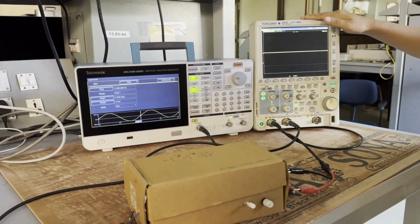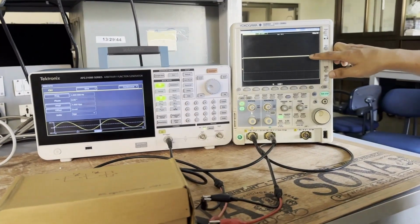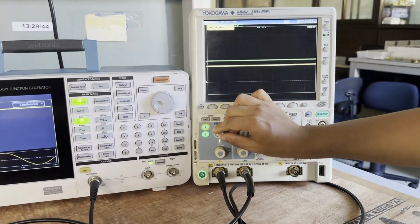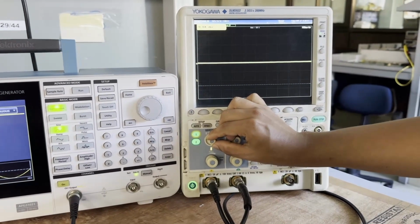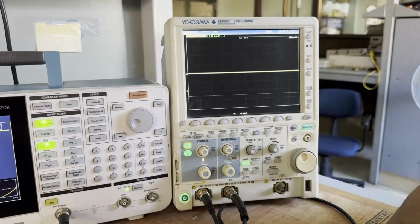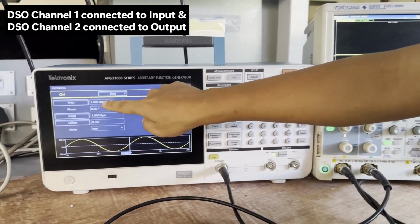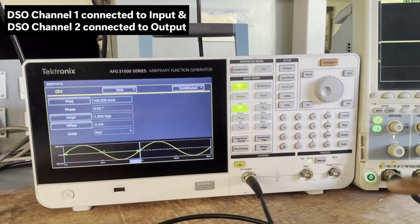So in the digital oscilloscope, now we can see a yellow line and a green line over here. So now in order to match the reference of the two channels, I will overlap the two and we shall see what responses we get. So now we shall start with a fairly low frequency. So here I'm going to give a sinusoidal input of 0.1 hertz frequency.